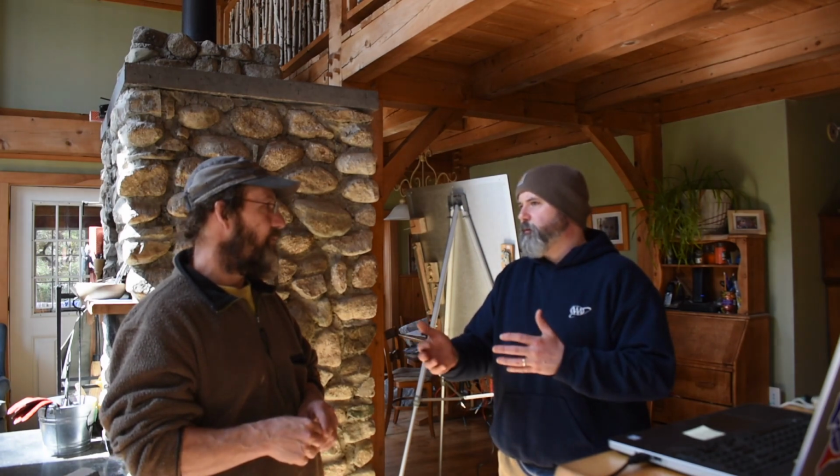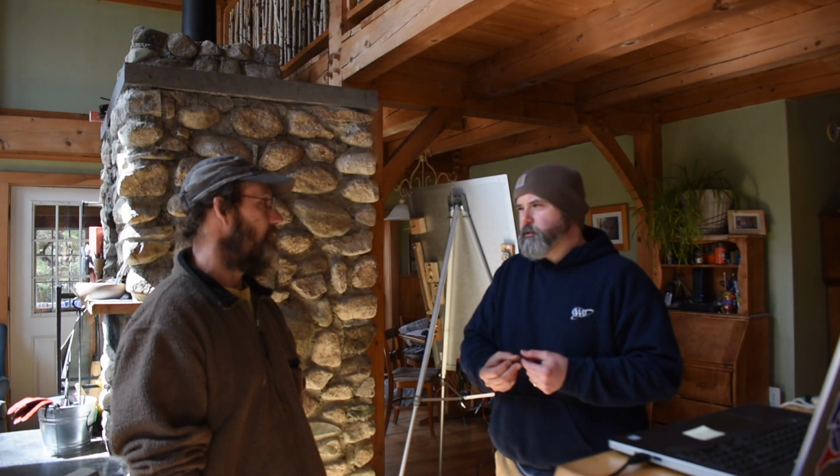Right. And you want to think ahead too. If you're building this from scratch and today all you need is lighting, so you're going to use a little gauge wire, but then two years down the road you want to have the inverter, the blender, the cell phone chargers, and there are more things you want. Try to think ahead. Don't think about today. Try to build it for the future scenario. Maybe it's a good idea to spend that extra money and get thicker gauge wire, because the devices you're going to run today, just lighting, will still work on a thick gauge wire. But if we build it for tomorrow, then we can add to it.